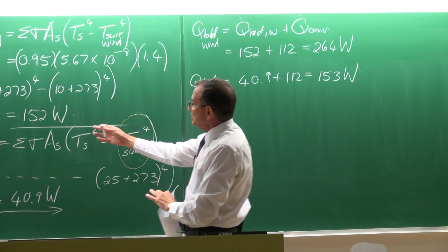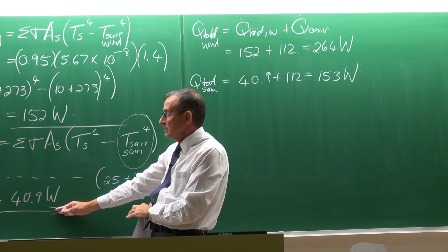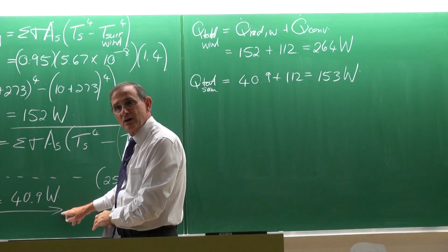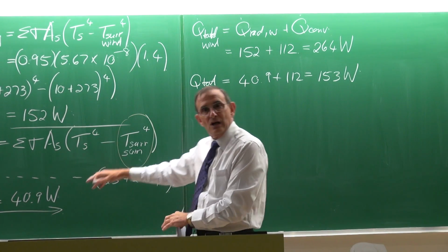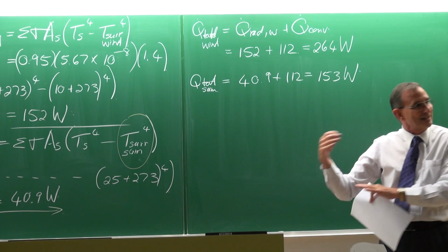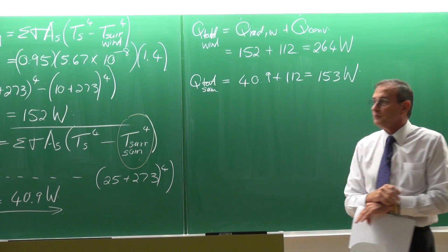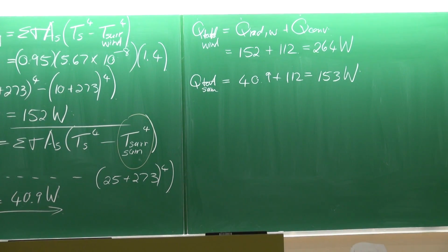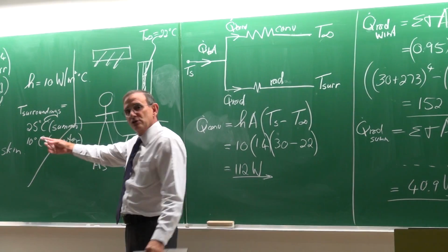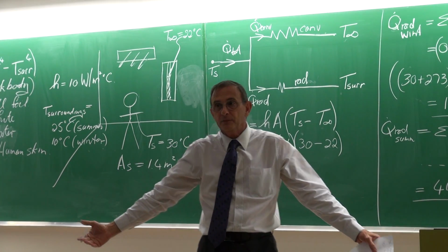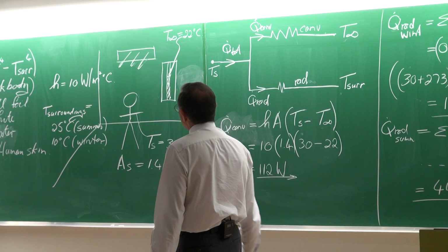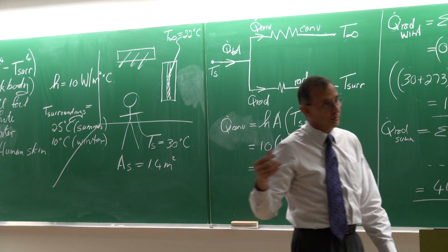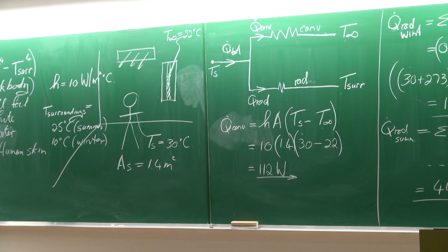Take note of the radiation heat transfer. In terms of the radiation heat transfer, the heat transfer rate is about 3 times lower from winter to summer, but the convection heat transfer rate stays the same. If you would be in your room and you would go out at night where nobody can see you and you stand outside, what is then going to happen? Your surroundings temperature, that winter temperature, is going to drop. It's going to be lower than 10 degrees Celsius.